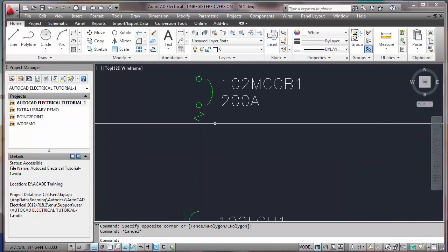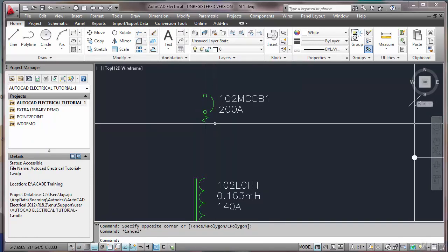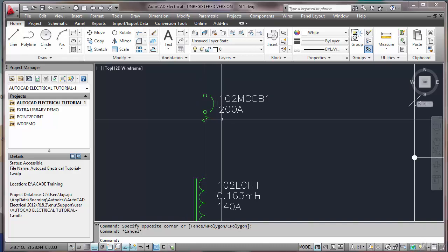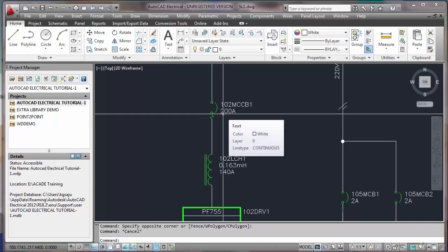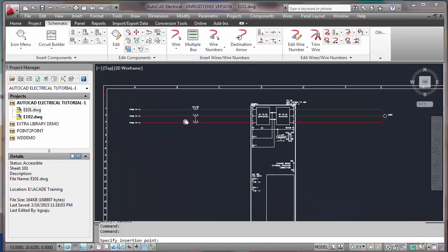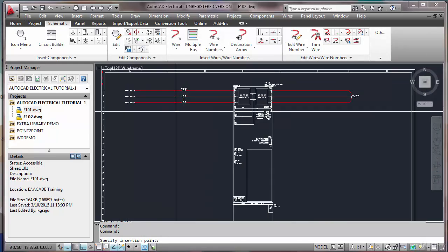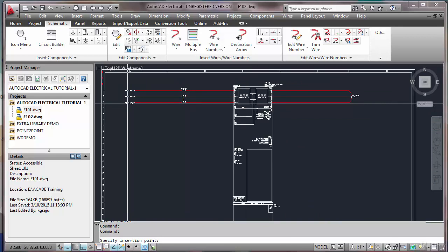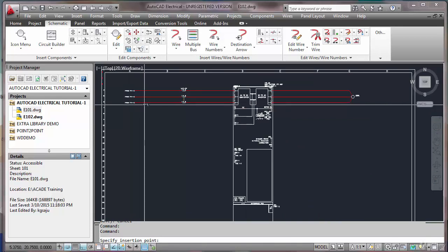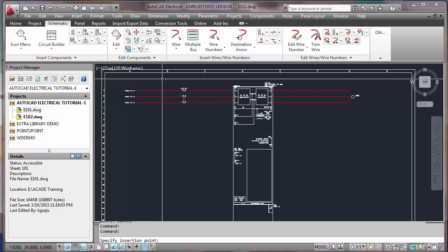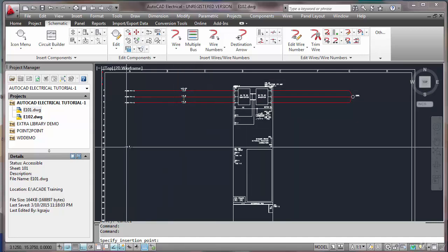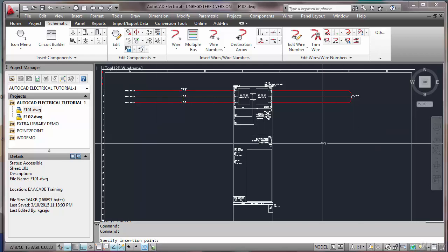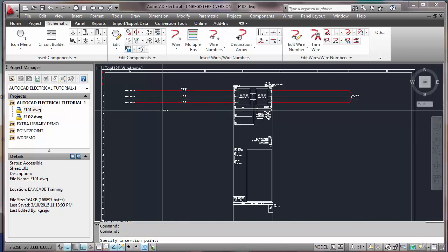These are IEC standards. Sorry, NEMA standards. So in IEC, if you want to make the drawings in IEC, it will be slightly different. The symbol, the representation will be slightly different. And while making the schematic diagram, if you see the flow, I am drawing it from left to right. This is how we make drawings in NEMA. If you are making the drawings in IEC, it should come from top to bottom. Everything should be from top to bottom. But in this case, it is from left to right. This is the basic difference of standard between IEC and NEMA.